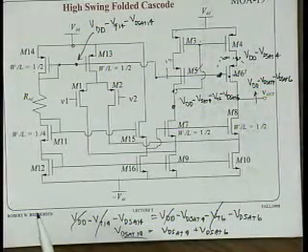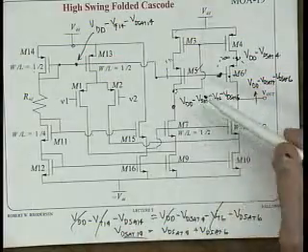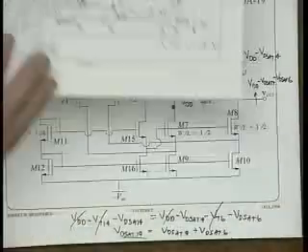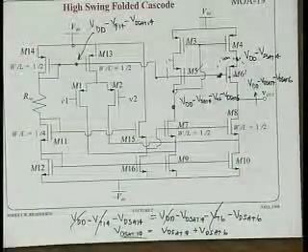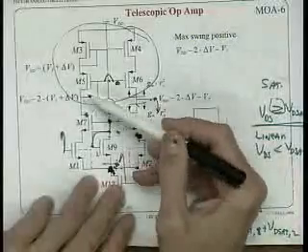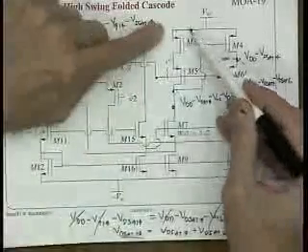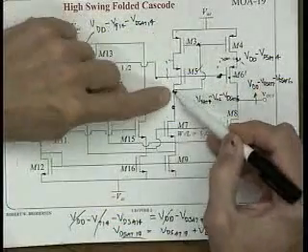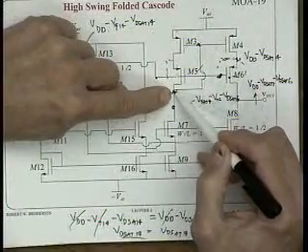There's nothing that sets that voltage, right? It's a really high gain condition. Basically, what do we normally have there? What we normally have here is diode connected transistors. In effect, this is a diode connected transistor. We're taking that gate voltage and bringing it up here and using it to bias this point.